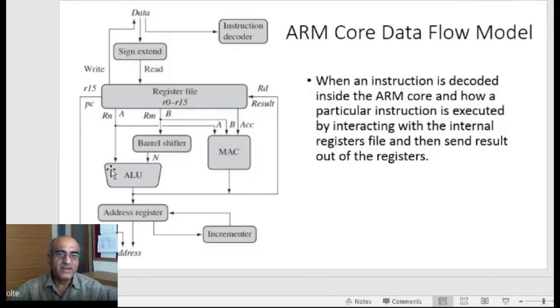When one instruction is executed, at the same moment the next instruction is decoded, and the one after that is being fetched. So three instructions at three different stages are executing within one clock.